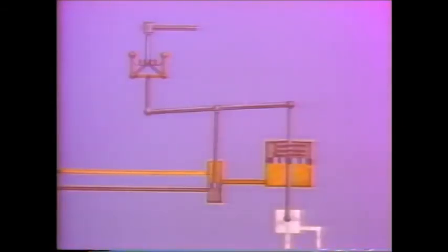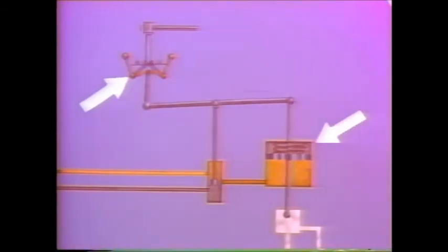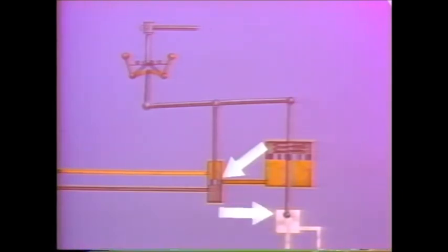The combined action resulting from the movement of the governor and the movement of the valve actuator act on the servo valve. This results in the closing off of the oil to the actuator and freezes the control valve at a new setting. During an increase in turbine speed, the flyweight governor action is reversed.